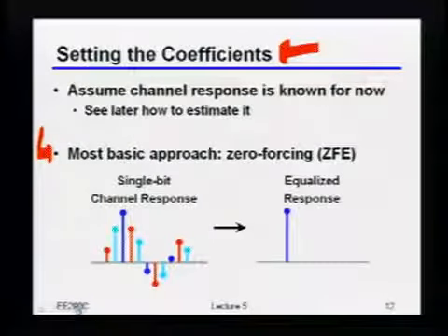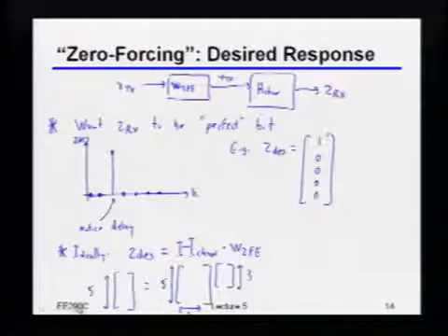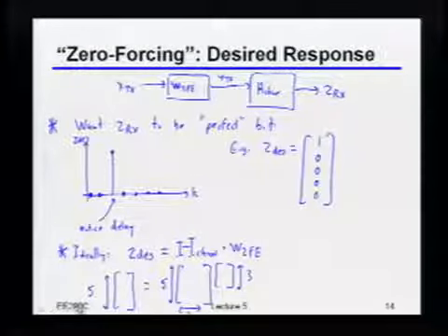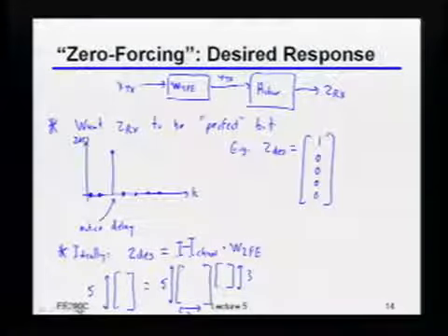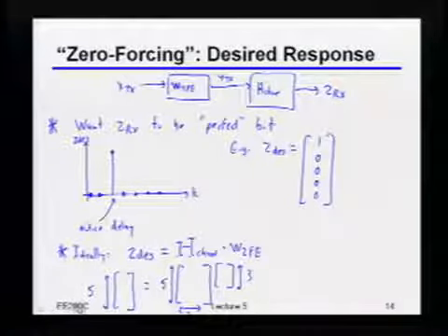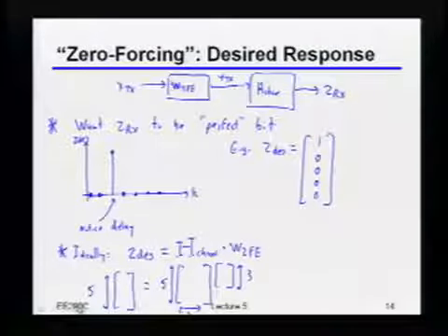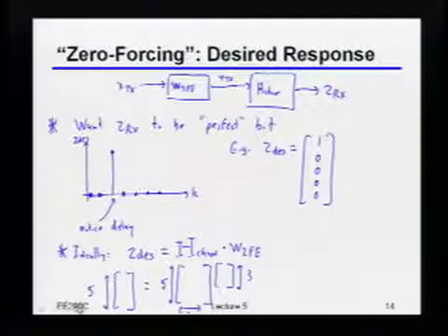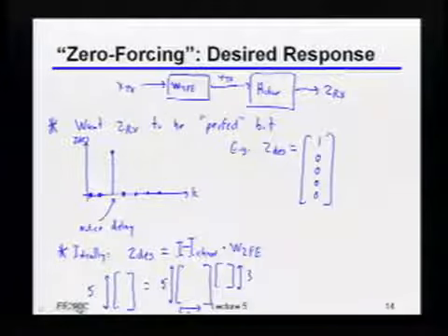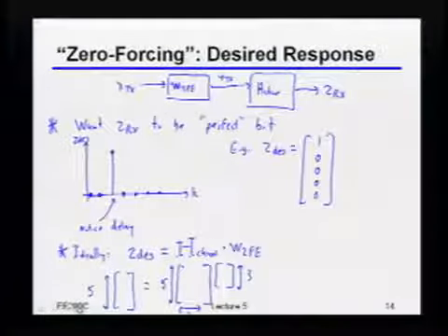Actually, I have a question about the number of taps. The more taps you have, it's kind of like you're going to translate into latency, right? Is there any case where you actually care about this latency? That's a great question. Indeed, there are many cases where you really do care about the latency. Specifically, if you're talking about something like a microprocessor talking to another processor, or a processor talking to a graphics card, you do care a lot about the latency. So if you end up inserting a lot of latency because of some equalizer or something you're doing, that could actually be a big deal.